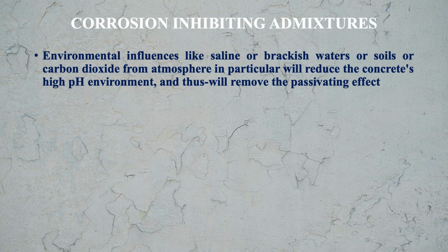Environmental influences like saline or brackish waters or soils or carbon dioxide from the atmosphere in particular will reduce the concrete's high pH environment and thus will remove the passivating effect.